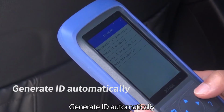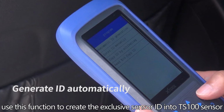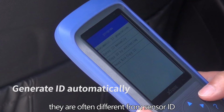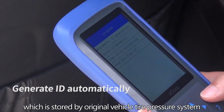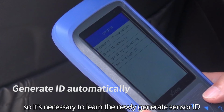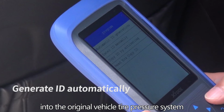Generate ID automatically. Use this function to create the exclusive sensor ID into the TS100 sensor. These IDs are random generation. They are often different from the sensor ID which is stored by the original vehicle tire pressure system. So it is necessary to learn the newly generated sensor ID into the original vehicle tire pressure system.